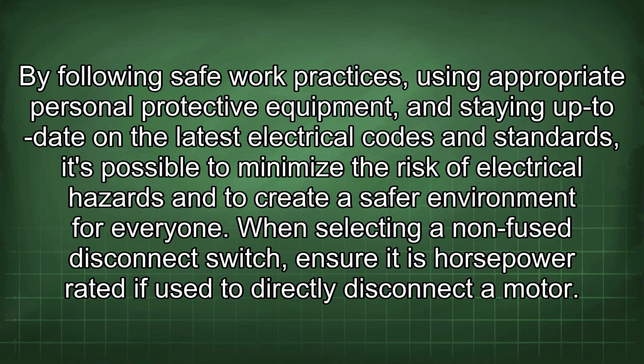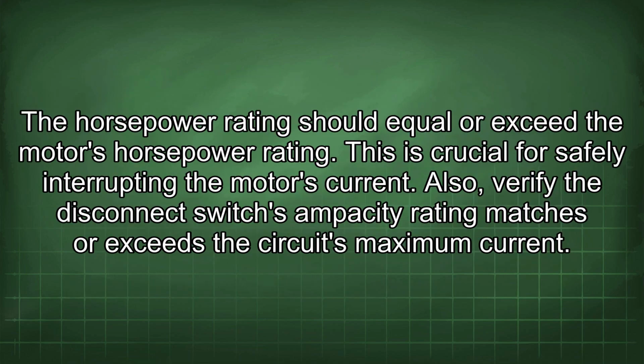When selecting a non-fuse disconnect switch, ensure it is horsepower rated if used to directly disconnect a motor. The horsepower rating should equal or exceed the motor's horsepower rating. This is crucial for safely interrupting the motor's current.